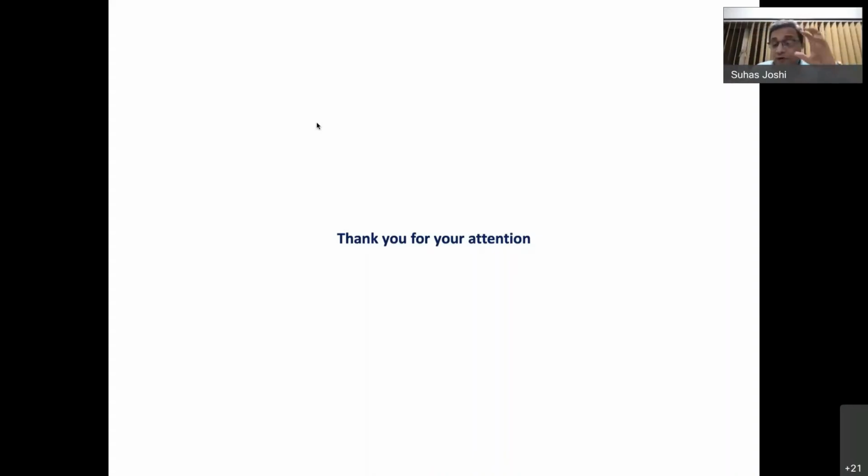I forgot the amount of acceleration it requires, but only then will you be able to leave a frozen chip on it. Otherwise, the chip will be cut off from the machining surface itself. You will not get a frozen chip. The tool has to be withdrawn very instantly. So that's a device we had made a long time ago, and we made very good use of it. Excellent. What was the second question?